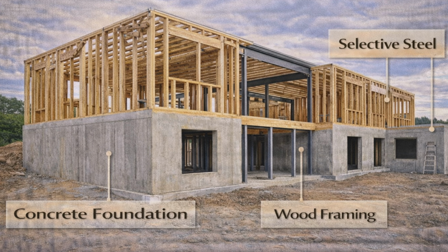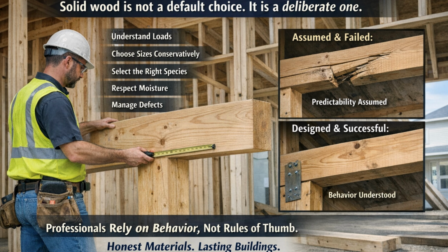Professionals do not choose materials emotionally. They choose them based on spans, loads, movement tolerance, moisture behavior, construction reality, and long-term maintenance. Knowing when not to use solid wood is just as important as knowing how to use it. Solid wood is not a default choice. It is a deliberate one.